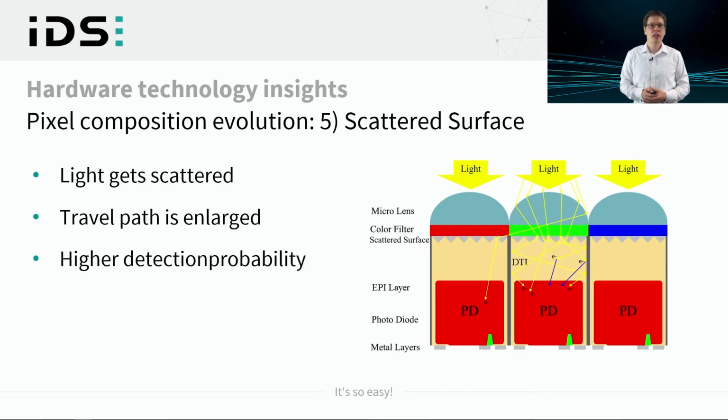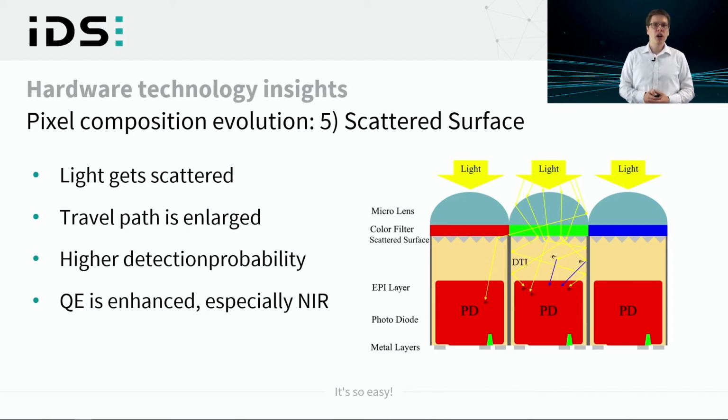Photons of different wavelengths, meaning for visible light the different colors, do have different absorption depths. That means bluish light with short wavelengths has a high probability to generate, right after a short path within the pixel made of silicon, already the countable electron. Light with a longer wavelength is absorbed with a lower probability, and thus a longer travel path is needed to raise the detection probability. Look what will happen with the very long wavelengths of the near-infrared spectrum in the example later. And keep this technique in mind.